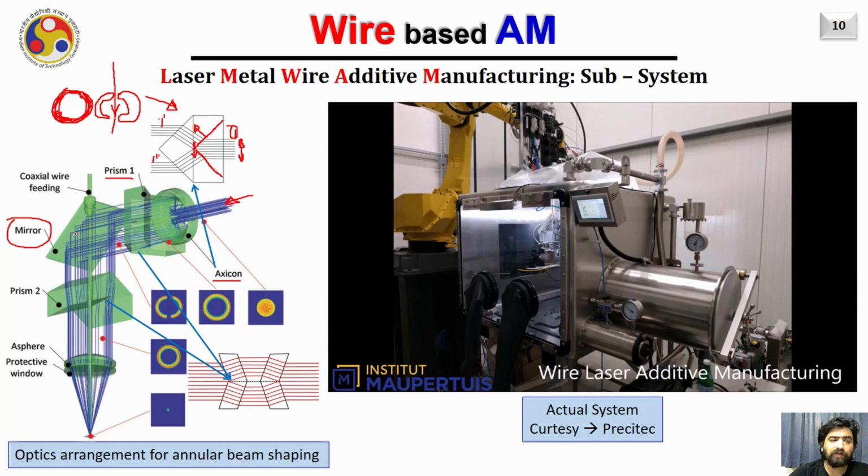At the time when it was getting deflected, we already have some space available, and we can insert a wire through this space. Then the next job is to bring this split beam back to the merged annular beam shape. So an inverted prism is used, and by utilizing this inverted prism, the split beam is again converted into the annular shape beam as you are seeing here.